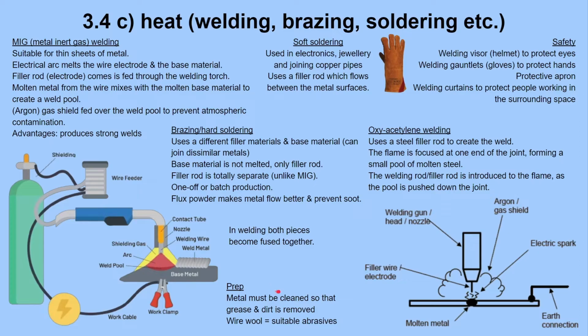And then in terms of preparing before the welding processes, you often have to clean the metal to remove any grease, any dirt, any debris. Wire wool is a good material to scrub the metal with. It's a good abrasive, so it removes any grease and dirt.